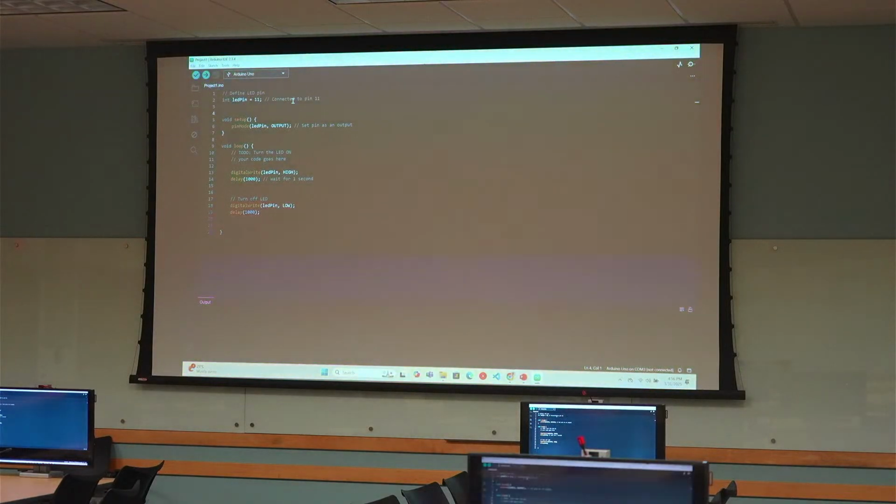Again, you're going to specify here the LED that you're using. Just out of curiosity, are LOW and HIGH constants, representing 0 and 5? Yeah, behind the scenes. If I replace either of them with 0 or 5, will it do the same thing? Yeah. You just use HIGH or LOW because it's more human readable, to maintain the code. But good catch. HIGH is going to be 1 and LOW is going to be 0, and it's going to work. But make sure you always match the pins that you set up here with the circuit, because if not, it's not going to work.